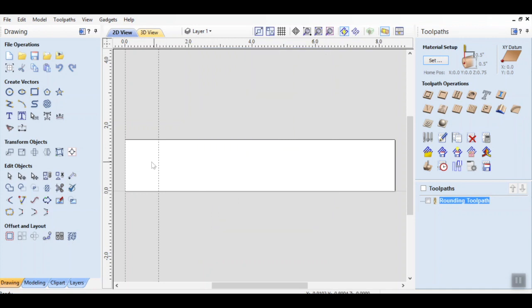It's going to fit in here. Every 1.05 inches I'm going to cut this out, and that'll let me part right there. And that part is going to be a peg. Well, to fit in the hole, I have to make the peg in here cut away. And the distance for that is going to be a 1/2 inch. Well, how do I represent that?